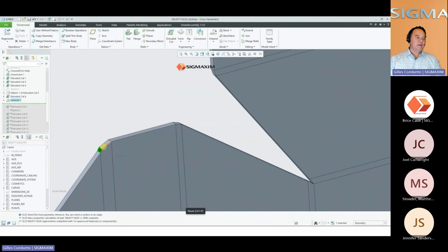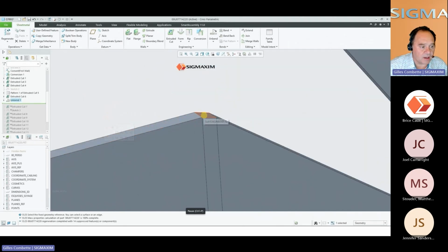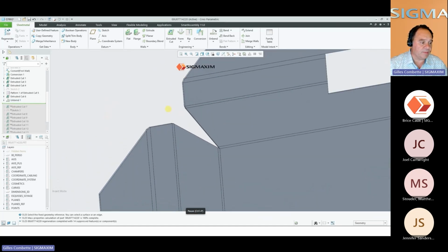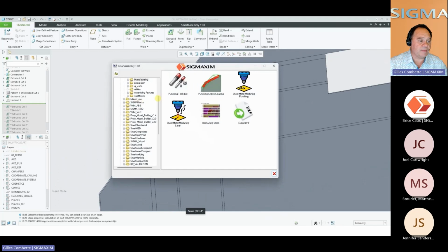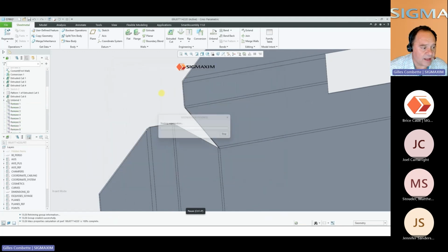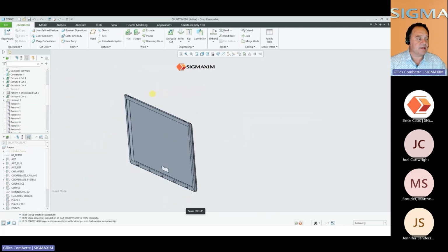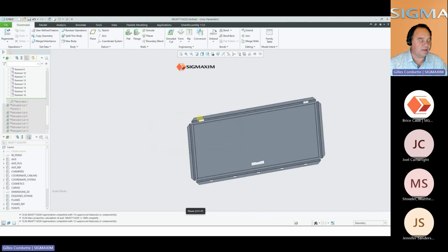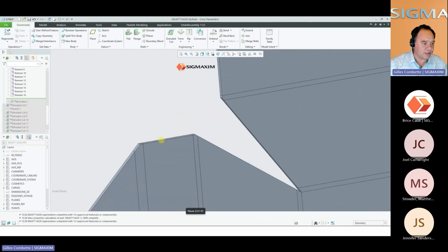You see here, there is some funky shape here and here. If you're using punching, even laser, those funky shapes will be realized, and you probably don't want that. So you probably want to have something that is more natural, more smooth. So basically here as well, we have the possibility to explore the full geometry of the models, whatever they are: sheet metal, plastic, solids, whatever.